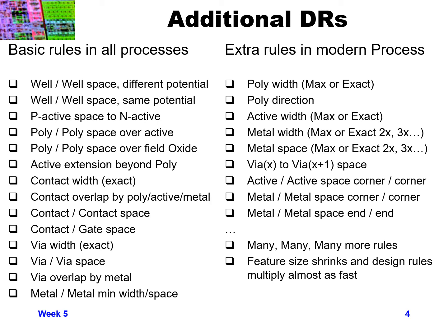Then making contacts to your actual silicon source and drain regions. Generally the contacts have an exact width that they need to be. It's not just a minimum width. Generally contacts are a very specific exact size.